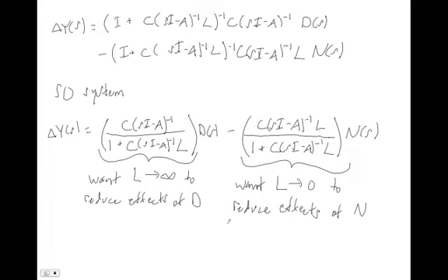The conclusion here is if L is small, we don't amplify the noise of our sensors, but this will only work if our model is very good and we have very low disturbances. Because, as an aside, the disturbances could be literal disturbances pushing on your states, or they could also be errors in your model. Those appear as disturbances. So that's what happens if L is small, but if L is big, we can reject disturbances, including modeling errors, but our sensor noise then appears in our states.